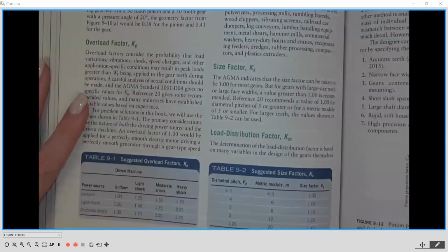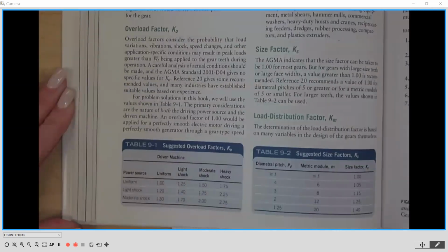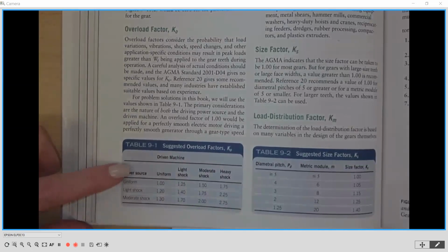So if we go to page 378, gear design is paging a lot and looking at charts and tables. And right down here, the overload factor KO is on Table 9-1 on the bottom of page 378. Okay. Now, overload factor. This is the probability of a jam-up occurring, or how volatile or smooth the operation is. So if we have a KO factor of 1, that means that it really has no effect on the stress, no problems. But anything that is more than 1 is going to have an effect on that. And the probability of something adverse happening is greater.